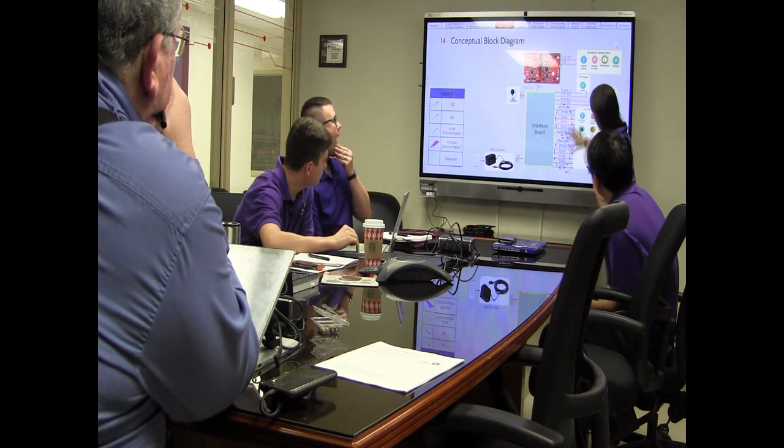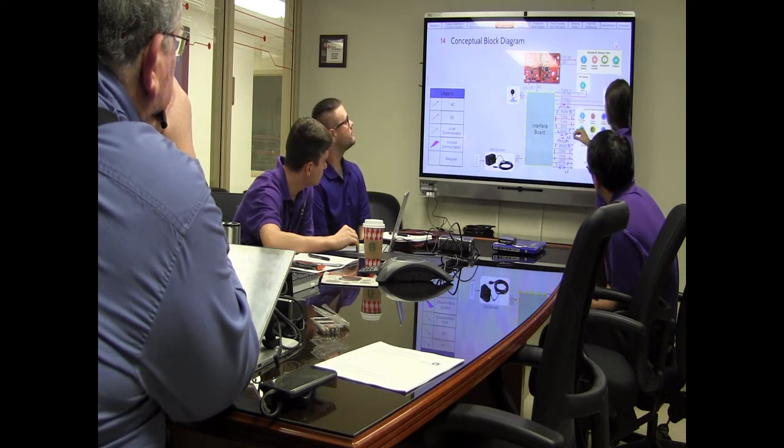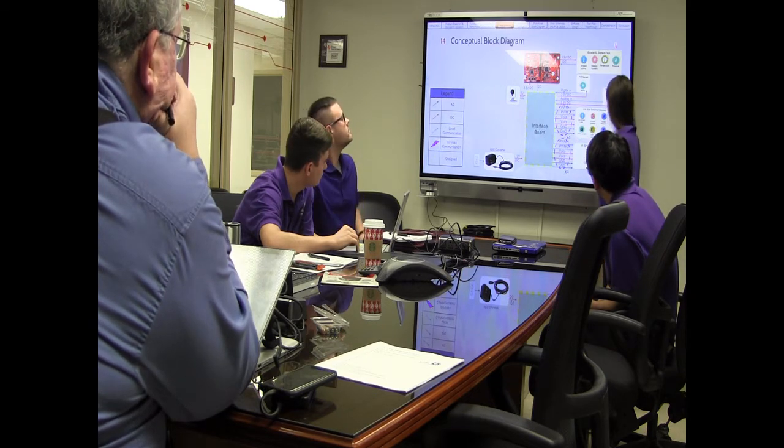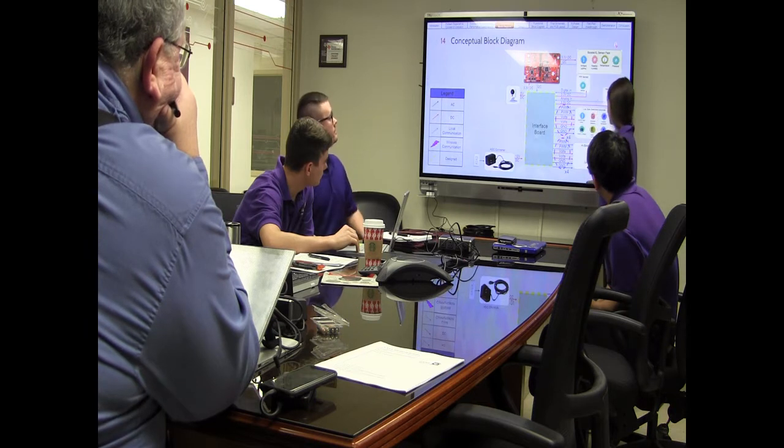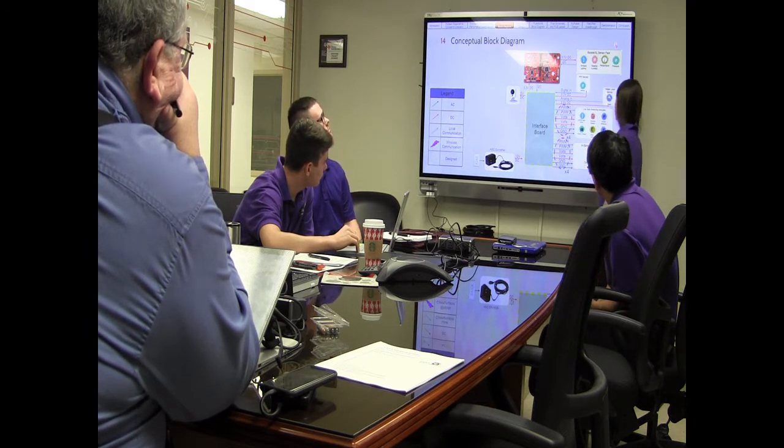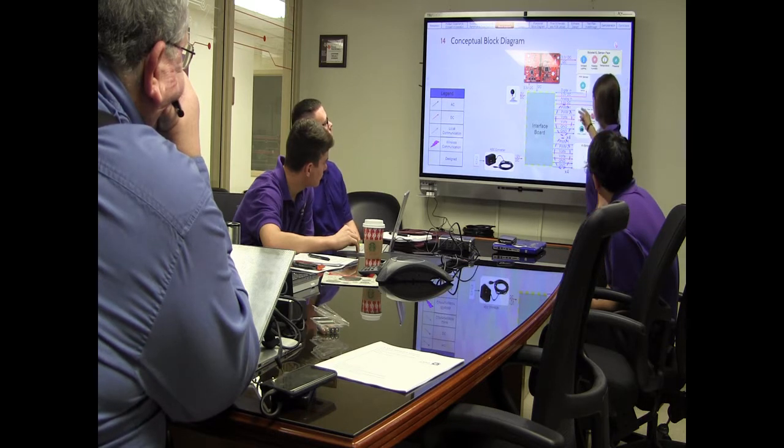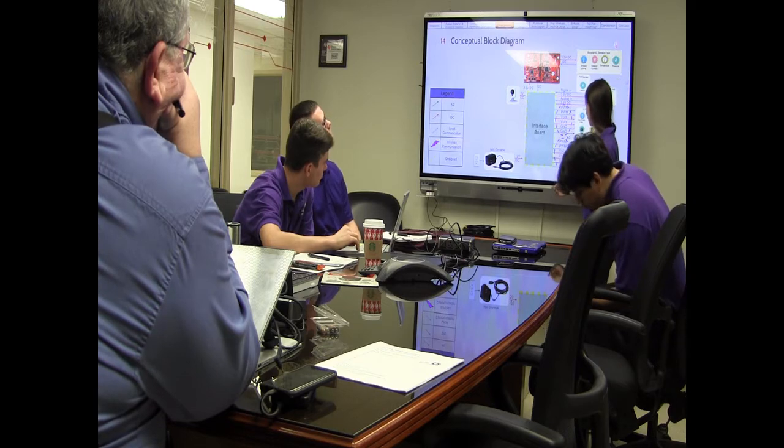So over here we're going to have 8 ports total. We're going to have 4 low side switching modules and 4 H-bridge modules. These are examples of what we're using them for. For our H-bridge modules, the only thing we're using it for is our control lights. We have a whole host of low side switching, which are mostly servo motors. We also have an on-off switch for our heat lamps. And that's going to send 2 PWMs, 2 voltage lines, and 2 ground lines.